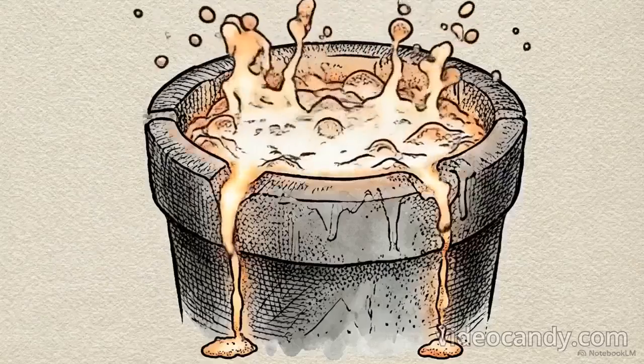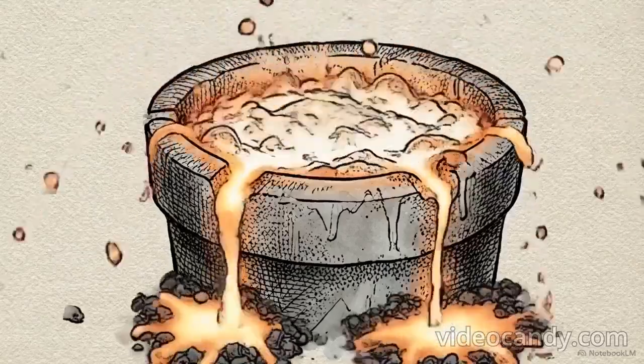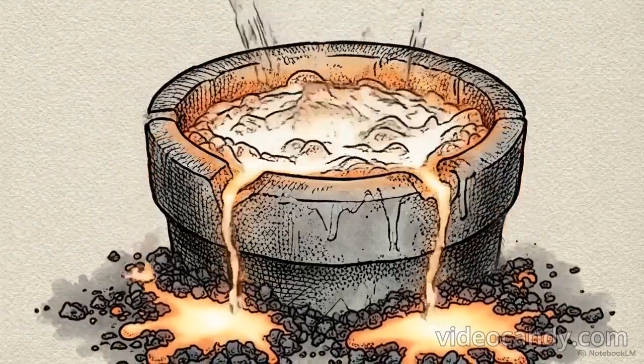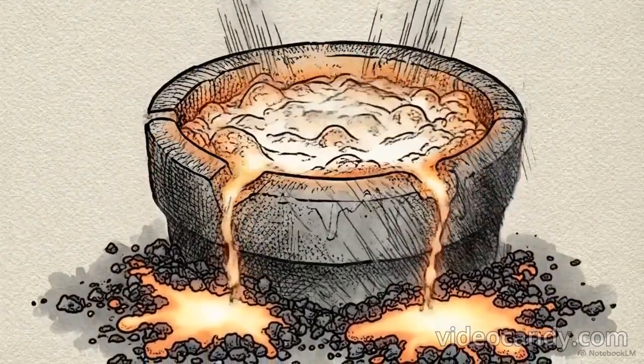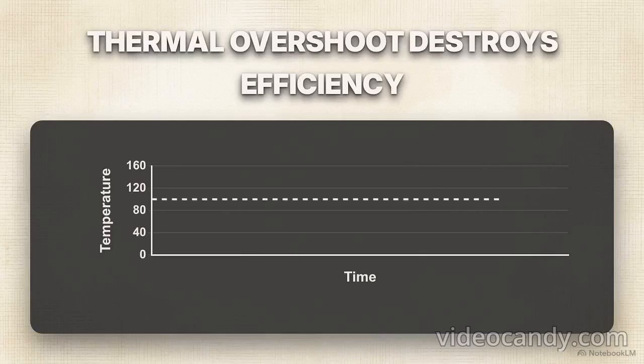In heavy manufacturing, thermal energy is a highly volatile physical variable. Without precise management, heat actively fights to destroy the very processes it enables. This graph maps temperature over time. When attempting to reach a set point, initial heat violently overshoots the target. The system overcorrects, oscillating in a hunting wave before stabilizing.